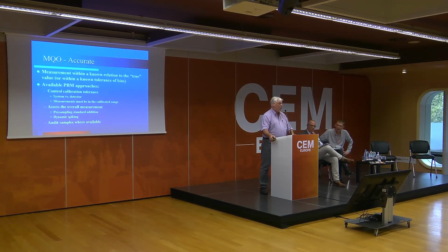Audit samples are important where you can get them. Method 29 is a perfect example. One of the things that I did early on was get my hands on some NIST coal fly ash SRMs, and then submit them to the laboratory as blind samples, and you would be surprised at what that revealed.